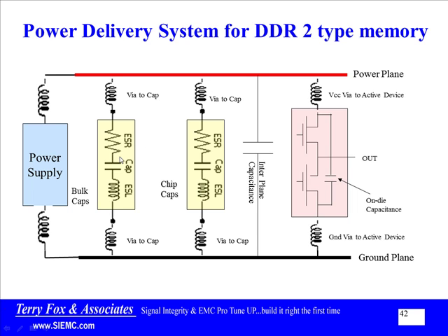The next, and if I look at what these will do for me, these will probably take a frequency response that probably gets pretty weak up around, say, 10 kilohertz on the power supply and probably bring it up into the tens of megahertz because of these capacitors. So at DC, the power supply is a low impedance, but as you get up in frequency, someplace between 1 kilohertz and maybe 10 kilohertz, typically the internal inductance in the power supply has got too much of an effect, and these just simply cannot supply the current at higher frequency.